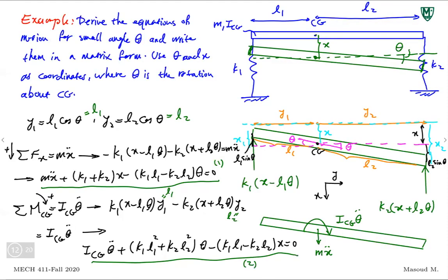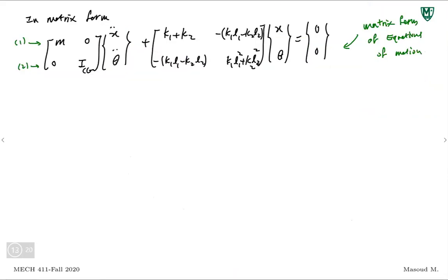So a little different: x, theta instead of x1 and x2. Still a system with 2 degrees of freedom. Geometry becomes a little tricky to find the forces and how much the springs are compressed. Once you get the geometry right, this is pretty much a dynamics problem. Find the summation of force in x direction, m x double dot, and a moment about a specific point. Write those, you get 2 equations. There's nothing in the horizontal direction, which we call y, so I didn't write that. Then rewrite the equation in matrix form. Remember, degrees of freedom now are x and theta.